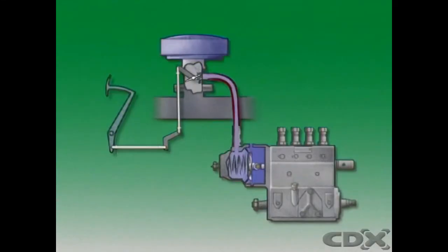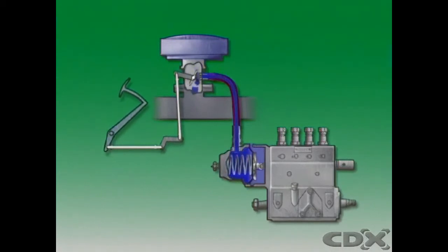Some diesels use a pneumatic or air-operated governor with a butterfly valve at the entrance to the inlet manifold. This butterfly valve is only used to operate the governor. It's not a throttle butterfly valve as seen on gasoline engines.